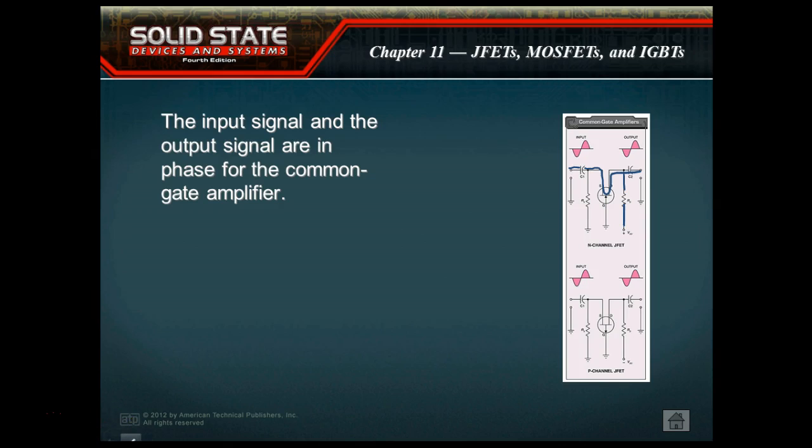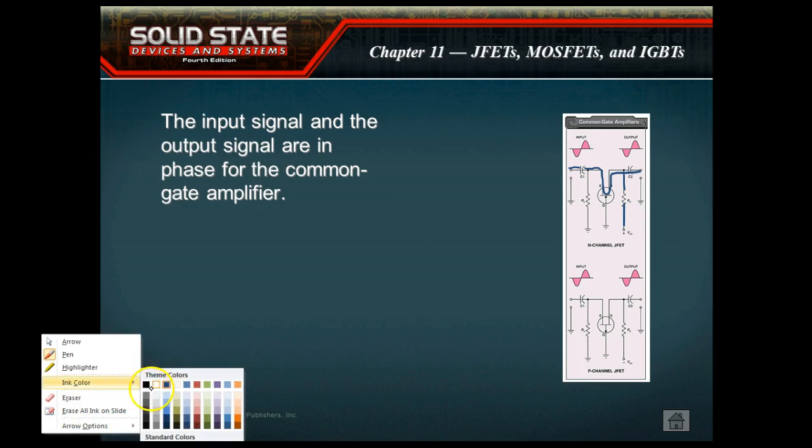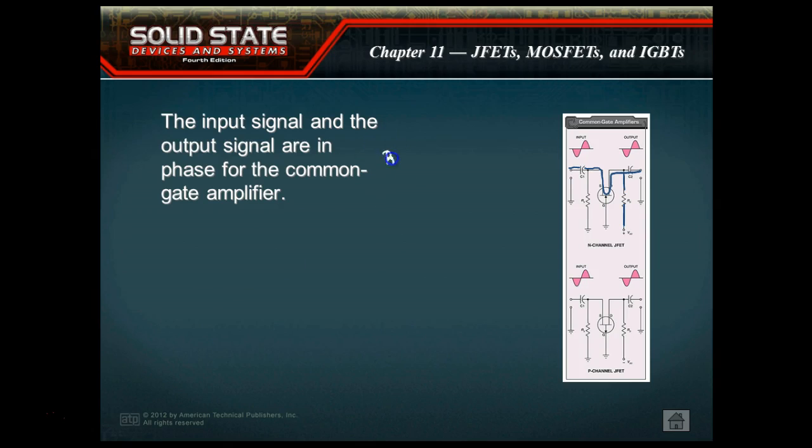So when we first started this, we didn't say they were the same, but we said they were comparable. So on a BJT and then a JFET, over here we call the control lead the base. Over here we call it the gate. Over here, our main current that we use, we refer to that as the collector. Over here, we refer to this as the drain. Over here, we refer to this as the emitter. The one that has the same basic function in a JFET is referred to as the source.